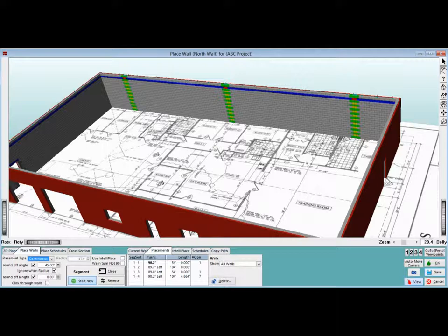This same process can be repeated in the vertical schedule for corners and wall jamb pieces. It is simply a matter of specifying the materials and where you are placing them in the wall. This concludes the chapter on the vertical schedule. The next chapter will cover assemblies and how to bring them into your project.